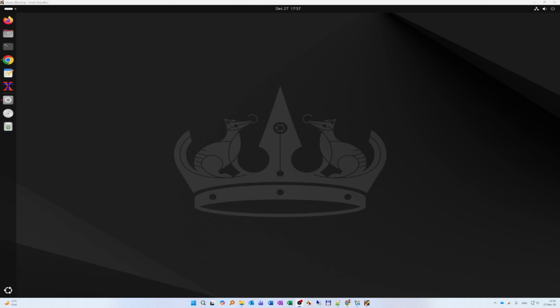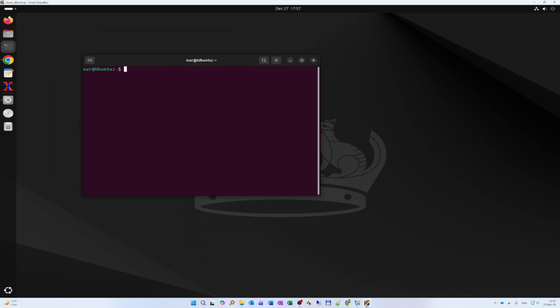Hi, in this video we are going to do inverter layout using Magic Tool and do DRC, LVS, parasitic extraction, and also post layout simulation. I might divide this into two parts. In the first part, do the layout, and in the next part, do DRC, LVS, parasitic extraction, and the layout simulation. So let's start with the first: look at the inverter schematic.